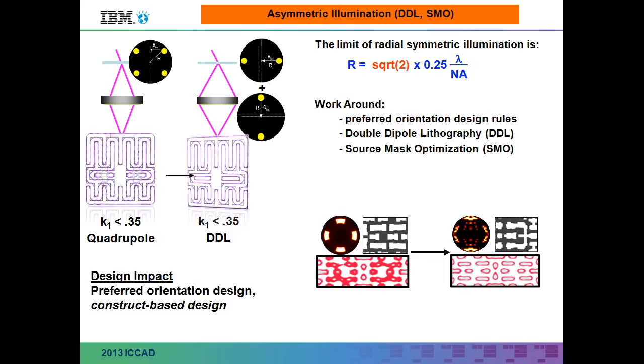But the illumination angle, right, that we derived a few slides ago is not this radial angle. It's the perpendicular projection, right? So for all vertical features, it's this angle that matters, right? The perpendicular projection onto the vertical line. For horizontal features, again, it's that perpendicular projection. So you can see immediately there's this factor of square root of 2 involved in this whole equation, right?